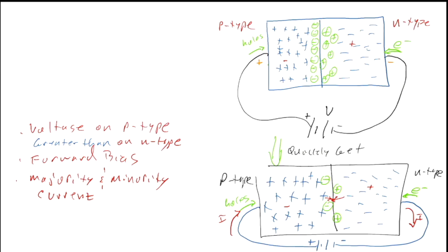A forward bias means that we have a positive voltage on the anode and a negative voltage on the cathode. Right? We had a positive voltage on the p-type side, and the p-type side corresponds to this end, and the n-type side corresponds to the bar and the short end, or that sharp end of the triangle. The n-type side is over here, and we had a negative voltage. So that's a forward bias condition.